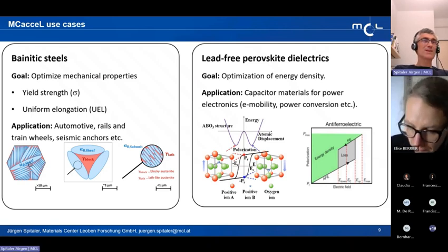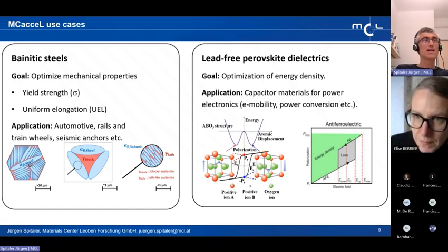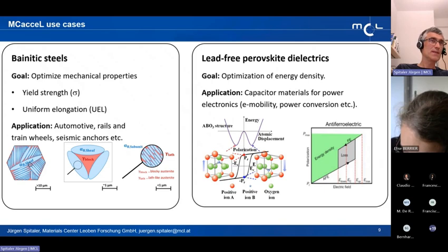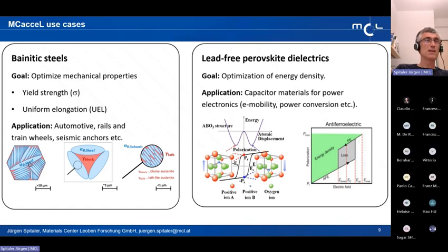Last, I want to mention the magnetic steels are also very interesting and beautiful in a sense because they have a very nice rich structure on different length scales. So it's not a uniform material, but it has a microstructure with different phases involved. On the microscope, we would see a structure like this here with sheaf-formed structures on the length scale of 10 micrometers. If you go deeper, you will find substructures and globule-like structures in the sub-micrometer range. This is not just beautiful if you look at it in the microscope, it's key for the performance of the material. That means how exactly this substructure looks like will also play a role in the material optimization we're doing.